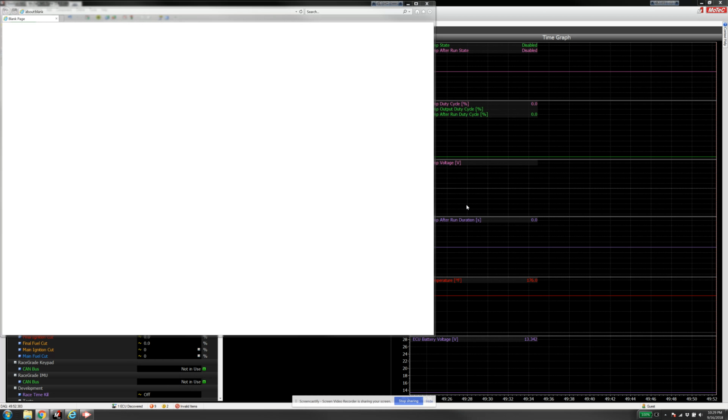I'm still working on ways to parse that data effectively myself, so I probably shouldn't talk about it in a YouTube video yet. Anyway, I want to talk about how, in the instance that you had the sensor, to get the data into your ECU or logger. And thanks to MoTeC being the wonderful company that they are, they have added a DBC import feature that I'm going to talk about real briefly, and also talk about how to integrate the sensor if you have an M1 ECU or you are an M1 build developer.